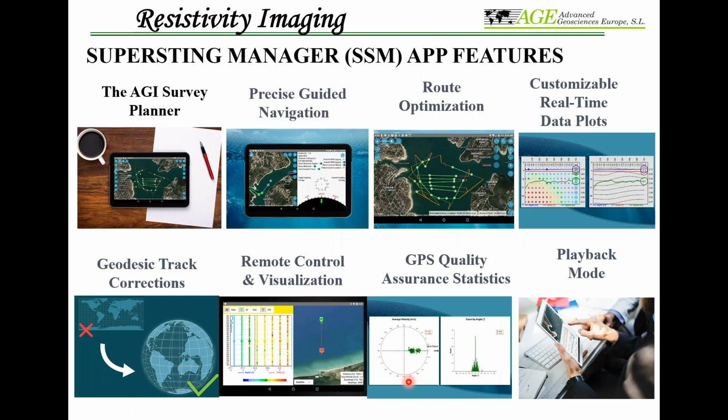So here are the application features, especially for marine. The same application can be used for land. As you know, you're using it mainly on land, but in marine we put a little bit more features on this. Like you can plan your survey before going out on the field. That means you put in your map, the tracking line orientations and the boat track directions, and you plan this, and then you start a simulation on this before going out.